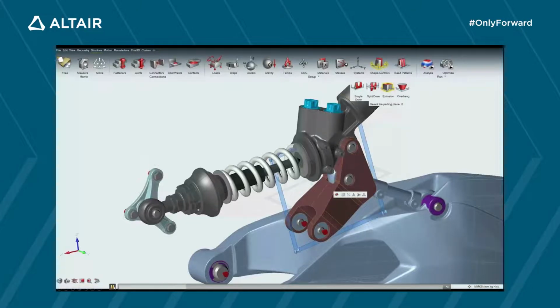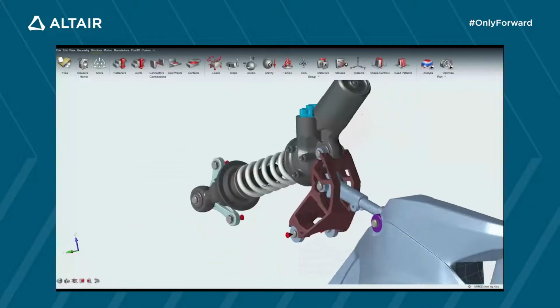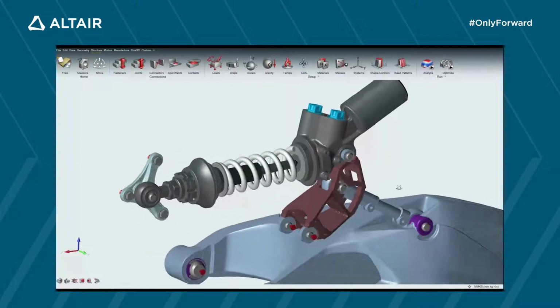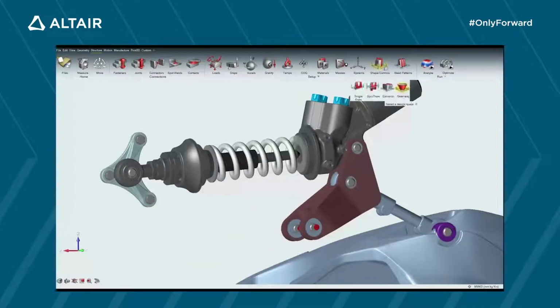Now, if we wanted to do an extrusion, similar process, we're clicking there, choosing our planes, applying that, letting the simulation run, and then we can see our design there. Now, obviously, for an additive manufacturing process, we're not so concerned about split draws or extrusions. We're more interested in print direction and overhang constraints.